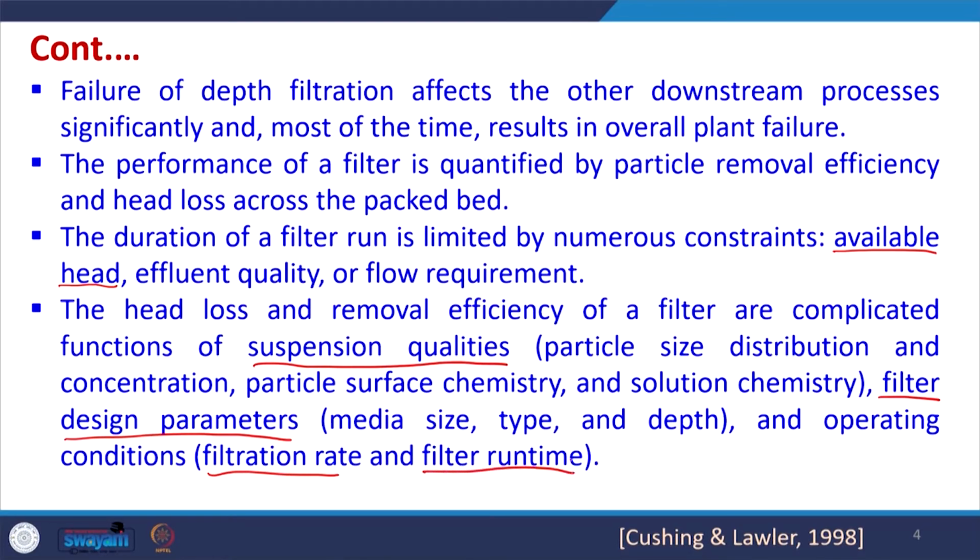Similarly, what are the operating conditions under which we are operating, what is the filtration rate, filtration time, and filter run time. This we can vary by having a number of filters in parallel. So, through that we can optimize or manipulate these variables as well. So, filtration rate, media type, media size, and the depth and the diameter of the bed, all those are the parameters that are in our hand and we can select them properly.